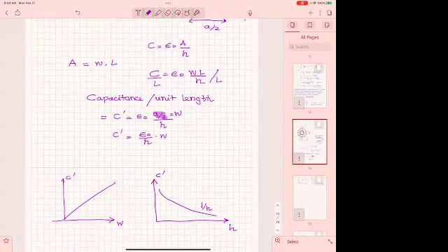Now, obviously, in all of these cases, as the one that I show you, these parasitic capacitances are created because there are other conductors around which are shielded. And obviously, these other conductors are there for whatever reasons, not as part of your cable design, of your line design.